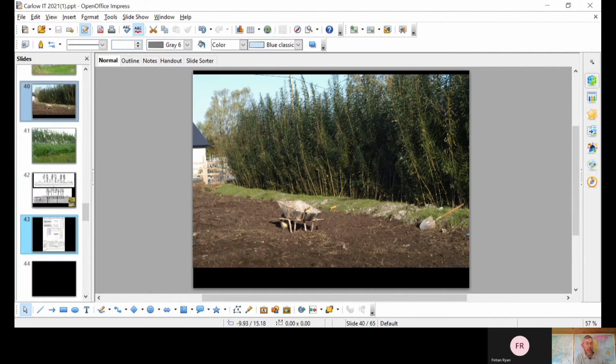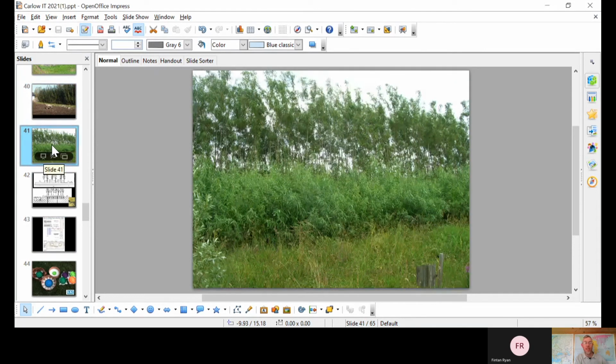Willow trees, as luck would have it, have about the same requirements for nitrates and phosphates as humans have in terms of nitrate and phosphate output in sewage. So you put it down to luck, or you could put it down to millions of years of evolution. Take your pick. So the coppicing regime that's used is that you'd strip one side of the basin, so 3 rows on one side, and you'd cut them all back on a given year. And then on an alternate year, you'd strip down the 3 rows on the other side.